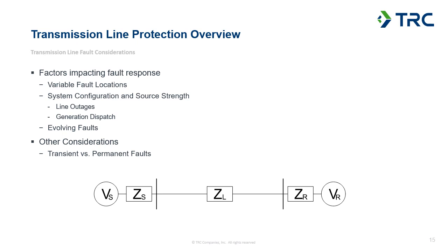Lightning may strike the transmission line and cause the line to trip off, but once the fault has been cleared by the protection, the lightning is gone, so the failure mode has been removed, and you can bring the system back online right away. That compares to something like an insulator failure, where the equipment has failed. Once you trip the line off for that reason, if you close it back in, that failure is still there unless you've sent a crew out to identify the failure and replace the faulty equipment.